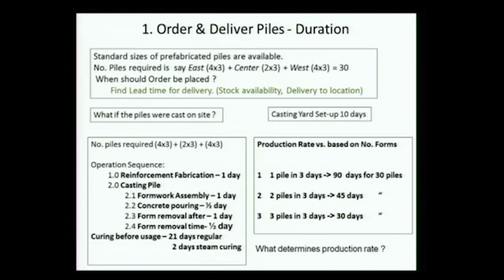Now I have not given you information on the depth of the pile or the dimension of the pile, because we are assuming all that is fairly standard. We should be getting into the detail if you were doing real planning, but right now we are just making an assumption for classroom purposes. So if I were to do a delivery, I just find it's going to take me 1 month from when I place the order to get the piles, then I have to place the order 1 month ahead of when I want the piles.